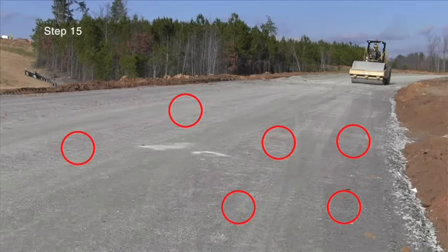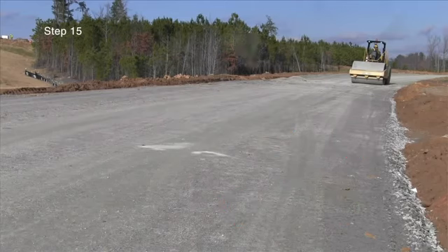The 3 calibration tests that evaluate high-density soil should use test locations that ideally have soil conditions that are close to the maximum density as determined by test methods D1557 or an equivalent. The range in water content should include low, middle, and high water contents. It is near the optimum water content as determined by test methods D1557 and D2216, or equivalent test methods.